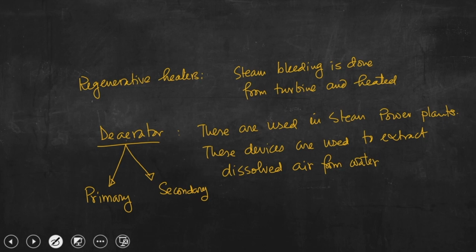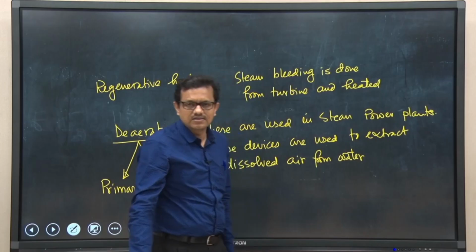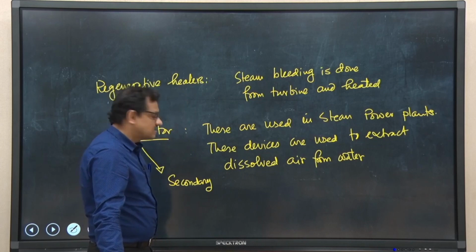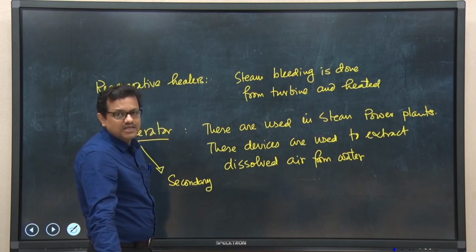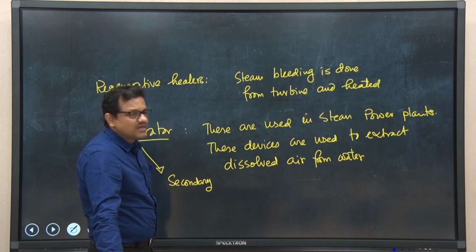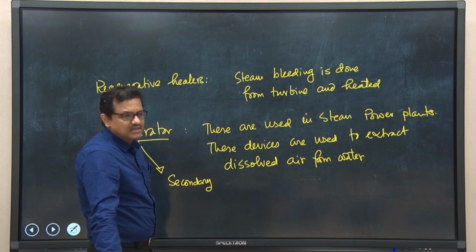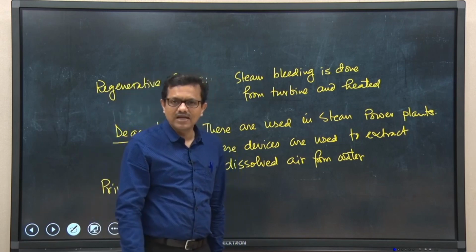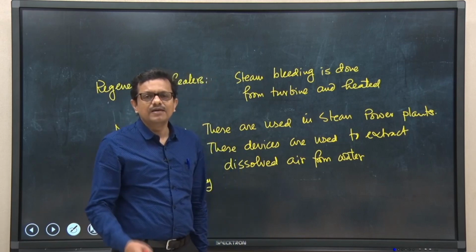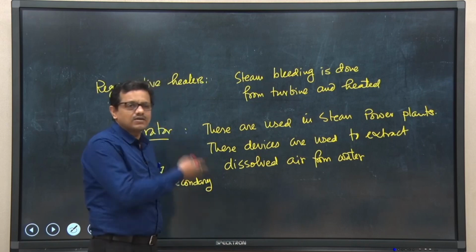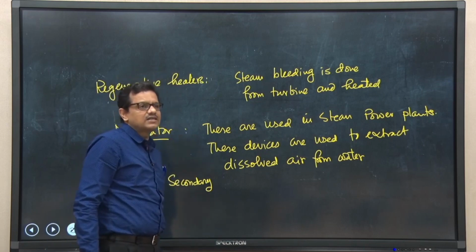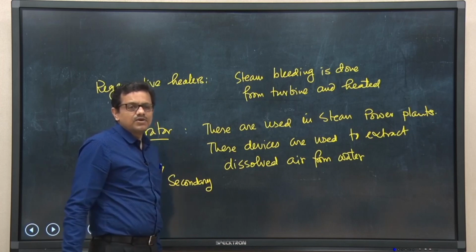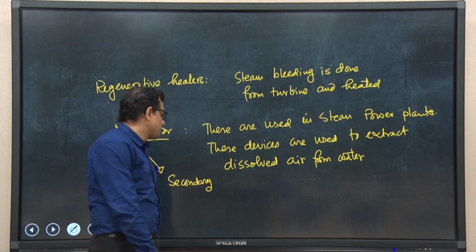I shall discuss this in one of the classes of this course, but this dissolved air should be removed from the condenser, otherwise the heat transfer rate will be affected, and if the dissolved air is pumped back to the boiler, air will create another problem from the operational point of view.